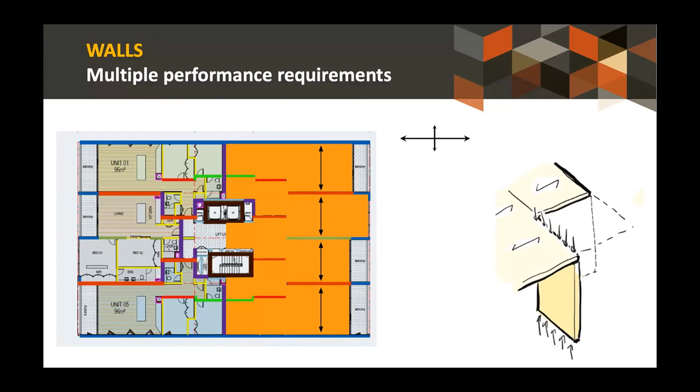But the direction that we're hunting for stability most is up and down the screen. And those walls that run up and down the screen will not have any beneficial load from our floors, which span in the same direction. And that's what the sketch on the right shows there. So you can see that where the floor spans onto a wall, we get some beneficial dead load, but where the walls are parallel with the floor span, we don't. And in this particular building, as is often the case, those are the ones that are oriented in the direction that's working hardest from a stability point of view.